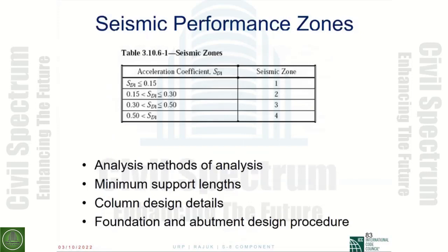What is the importance of the acceleration coefficient for the S sub D1? It will give you what are the seismic zones. We have 4 seismic zones. If you are in a high seismic area, most of the time you will be in seismic zone 4.